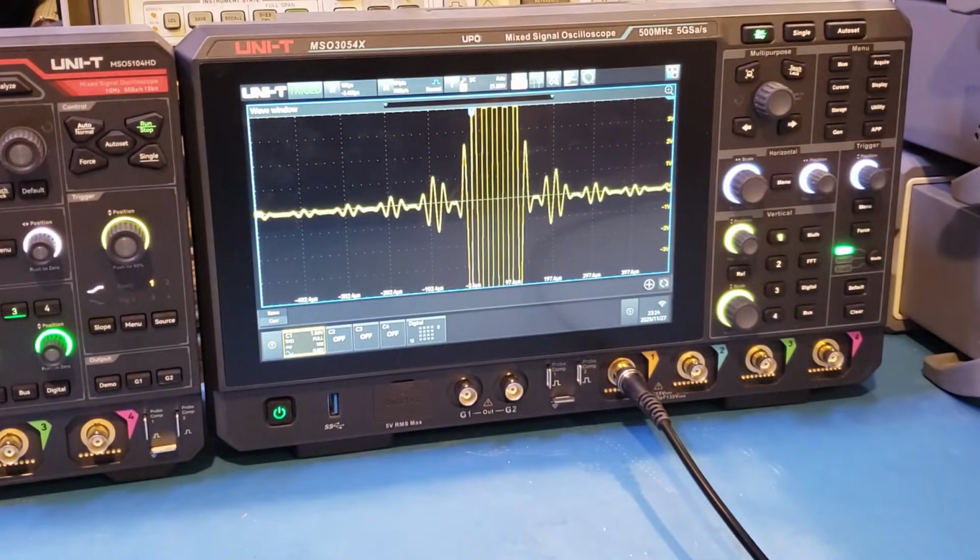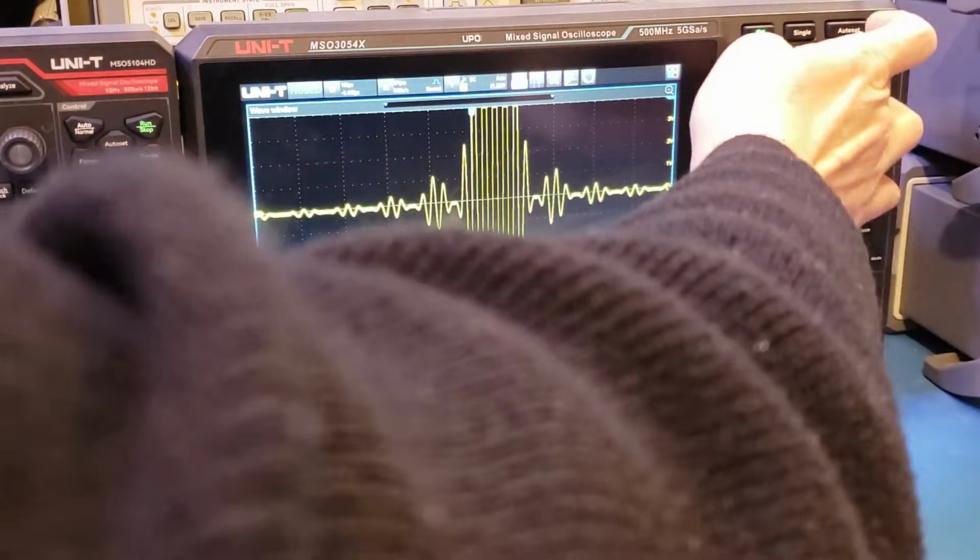That's because right now we're digitizing this section of the signal with all 8 bits. So for this reason, in most cases, you can actually get by with an 8-bit scope, but you will need to set a vertical amplification such that the signal of interest take up as much of the amplitude as possible for the best resolution. And sometimes you may need to take multiple measurements to achieve that. But for transient signals, especially if you are only able to capture that once in a while, it's going to get much more difficult. So pretending this was a transient signal, let's reacquire that.